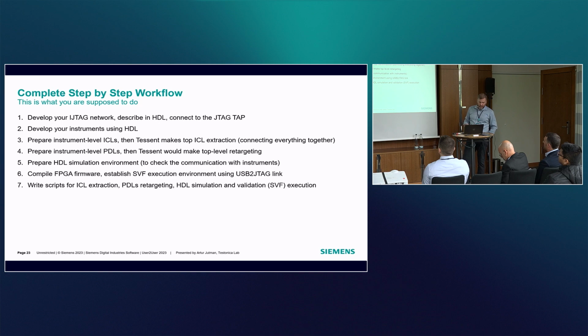So if we look at the step-by-step workflow, first, you need to develop your IJTAG network, describe it in HDL, and then connect it to the JTAG test access port on the FPGA.